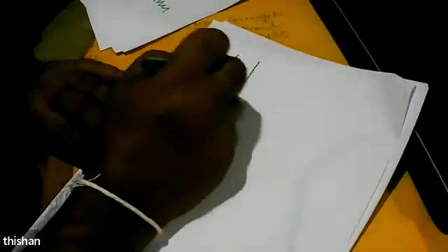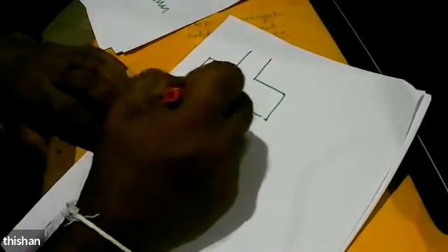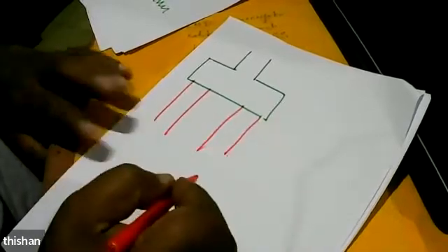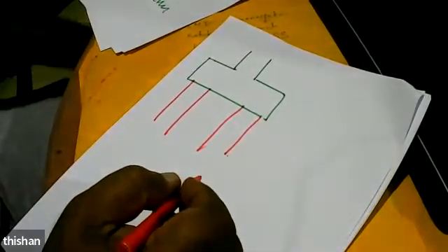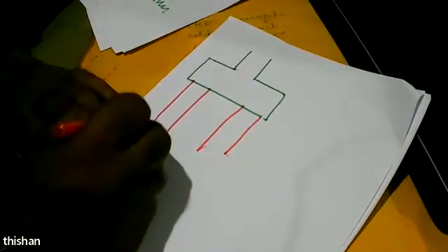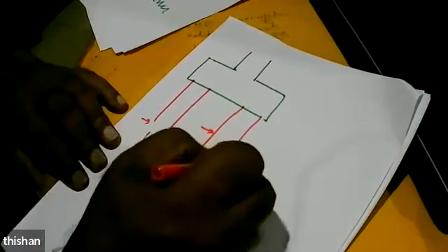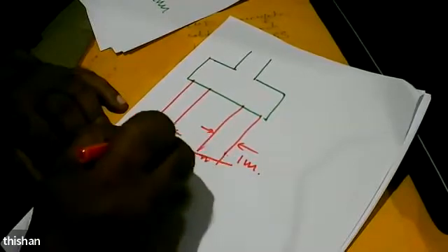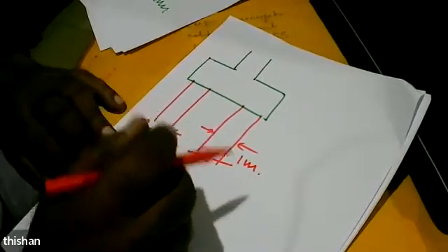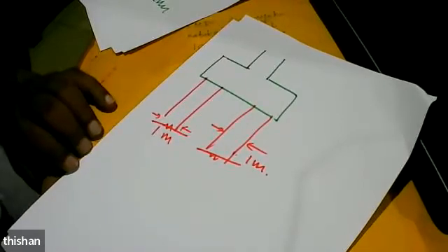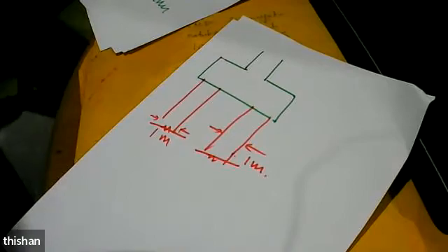And when you have a foundation, you might have to think about the slabs, the piles or the rafts. So strip footings will not work for these large buildings. So we need to have a set of piles. And here I can use, say, 1 meter diameter. We'll get 1 meter diameter piles, 1.2 meter diameter piles.